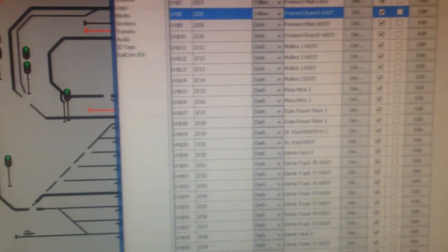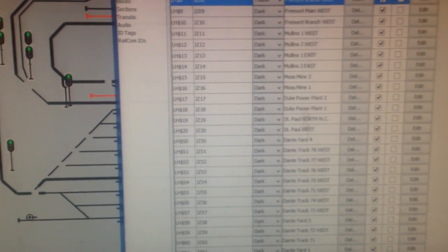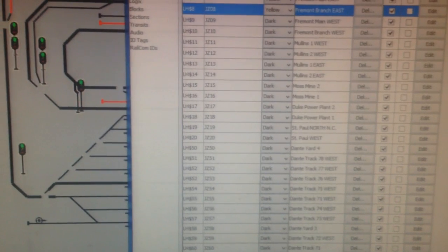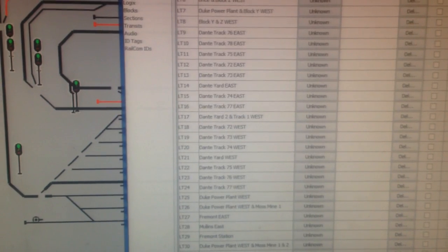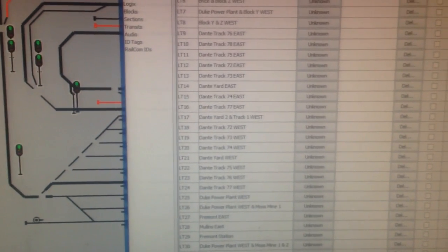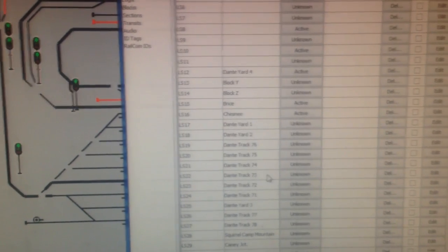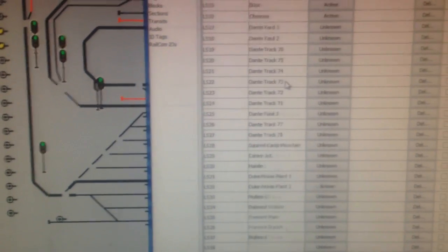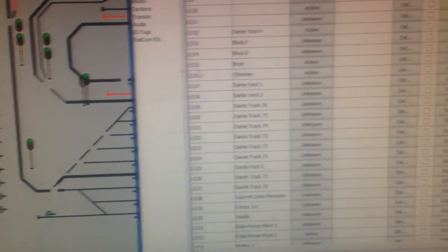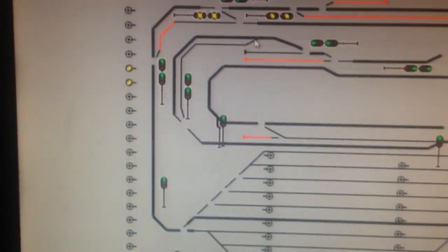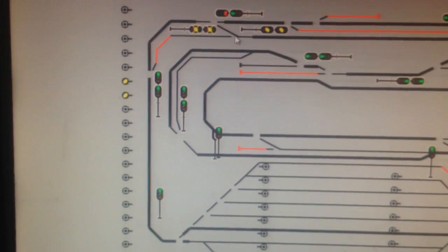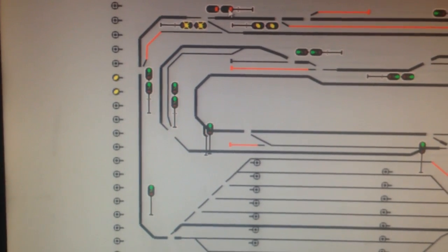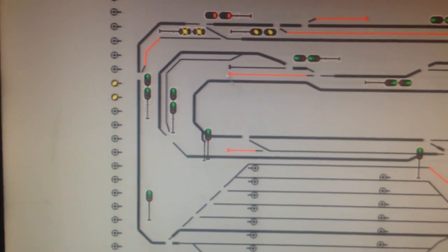So as you go through and you identify, it's something you have to learn with JMRI. I gave it all my locations, my information, the addresses when I set it up. Here with the turnouts, I'm giving it information on where the turnout addresses go. Let me see, sensors. Sensors are for the block detection. So all the sensors, you identify them going through. Then when you get to the map, you say stuff like, flip a turnout. Let's say here, you hear that one, see it goes.